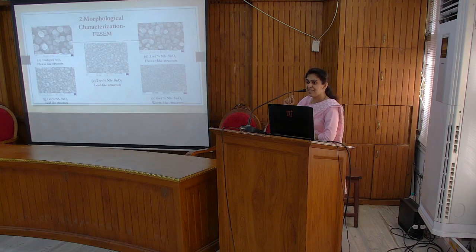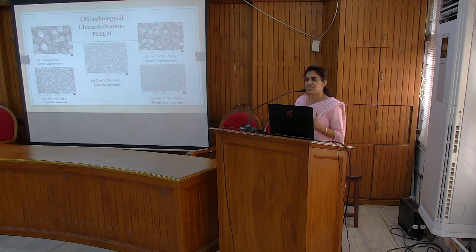It might have a better chance to act as a good sensor. Yes, for sensor applications, that is the conclusion. That depends on the dopant concentration and the ambient, how we are forming this sample; the substrate temperature, everything can affect this morphological structure. This particular sample was formed at 345 degrees Celsius.